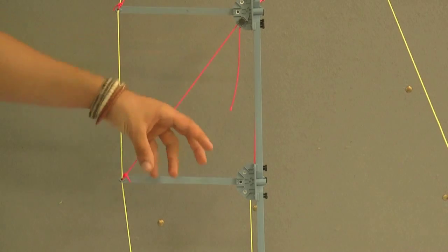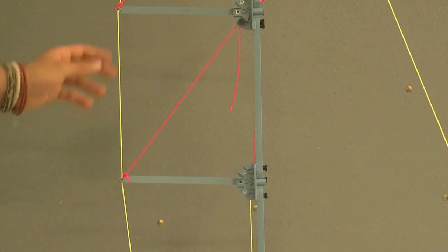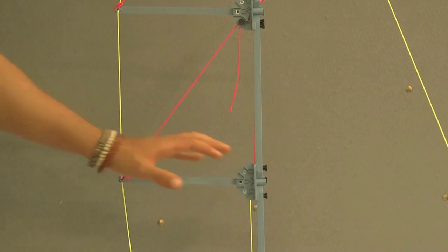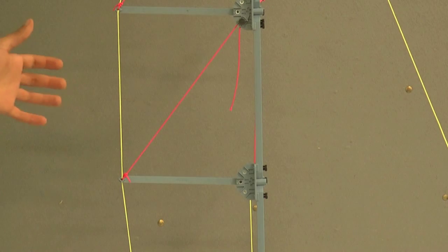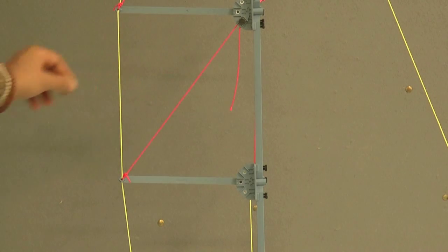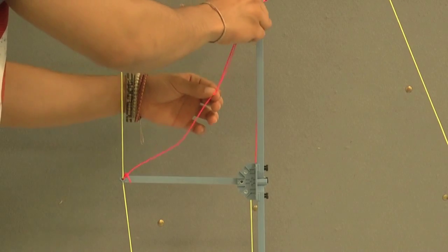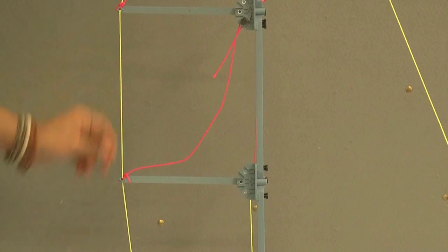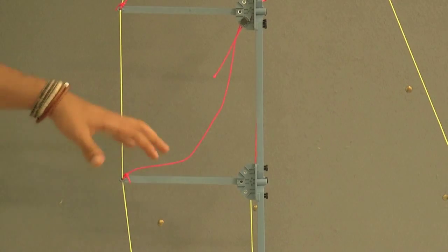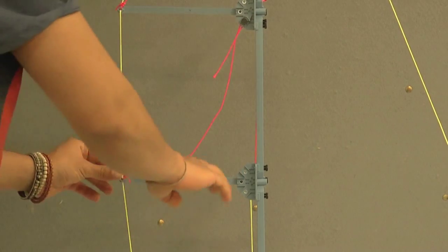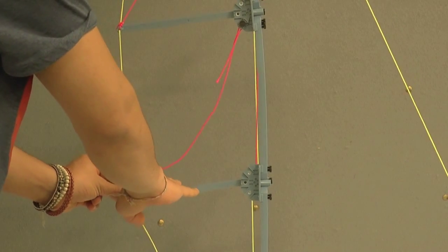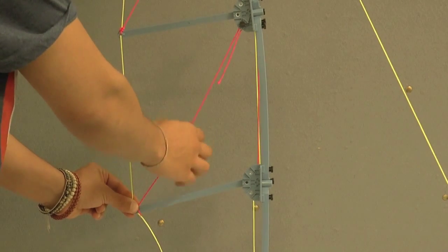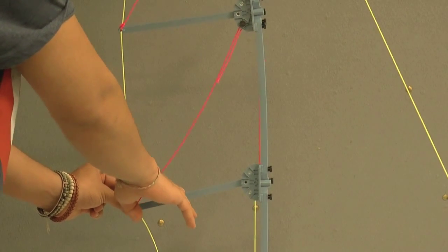Okay, we're going to start off by looking at this one member, this one yard arm, and see how it reacts under its own self-weight. Now, the yard arm, we can assume it has a constant cross-section, which can be modeled as a uniformly distributed load. And how we're going to go about this is we're going to loosen this one cable here, as if it weren't there, and we're going to apply a load that's going to be the self-weight of the member. Now, what happens when we load it, as we can see, the diagonal cable, the diagonal cord, lengthens and gets tighter and tighter.